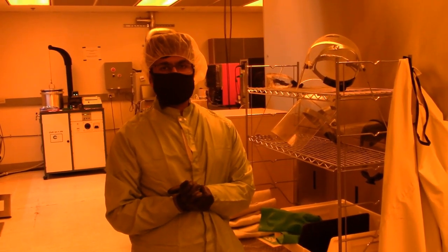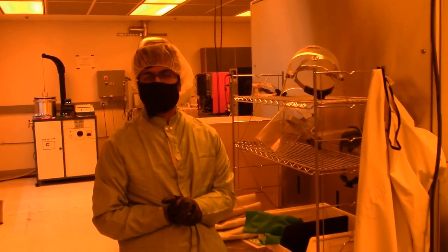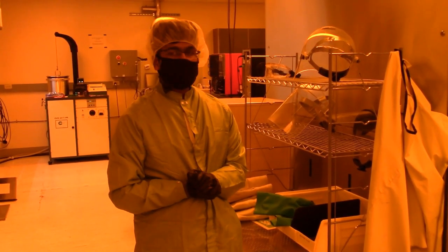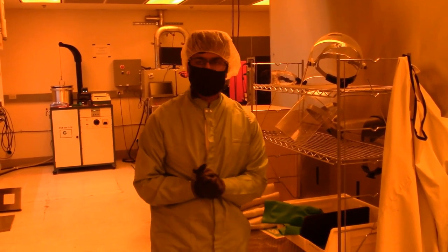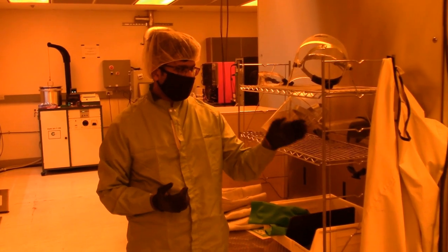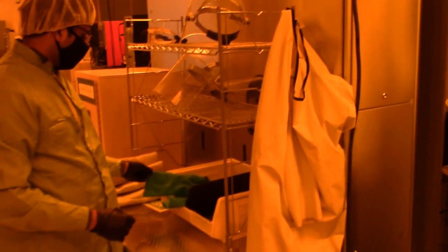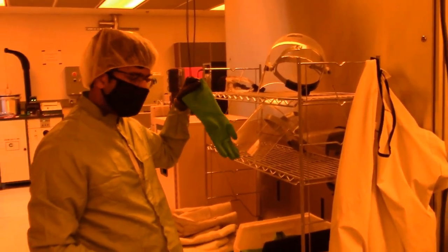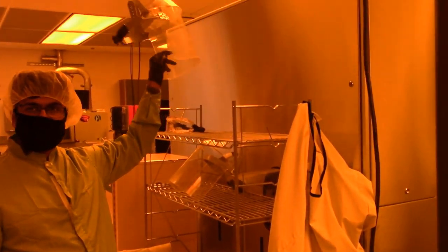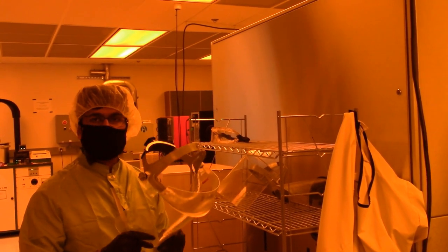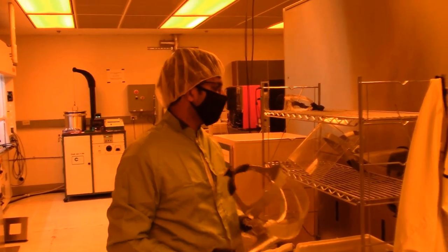Okay. Now that we are going to use buffer oxide etch to etch oxide, there are a couple of things to keep in mind before actually proceeding to the step. Since hydrofluoric acid is very poisonous and dangerous, it is important to use personal protection equipment, and acid protection equipment such as this over here, and nitrile gloves which provide a decent amount of protection to hydrofluoric acid. It's also important to use a face shield to provide splash protection, to make sure that it doesn't get into your eyes.